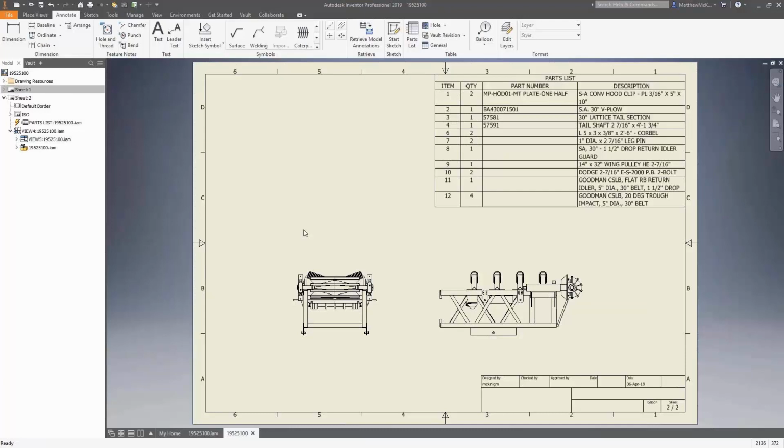And we could, if we wanted to, this is a very large assembly, we could now turn on defer updates. We could work away on this drawing, work back with the assembly, make a number of changes, come back to the drawing, keep on working on it. And then it wouldn't be until we actually turn defer updates off again that those updates would flow through to the drawing. So again, another practice to help you improve when working with large assemblies inside Inventor.